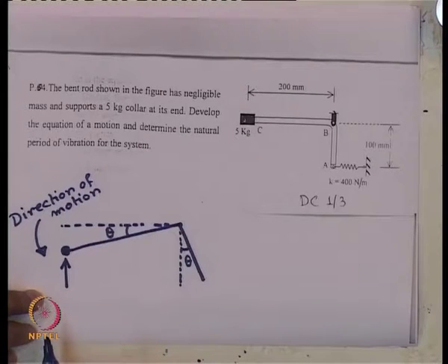Downward weight will act, not the inertia force. Now, why are we not showing weight? Because we know from our previous lecture that in case of vertical mode of vibration, weight is getting balanced with respect to its static displacement and things like that. So, after attaining static equilibrium conditions, we are proceeding further for this case.